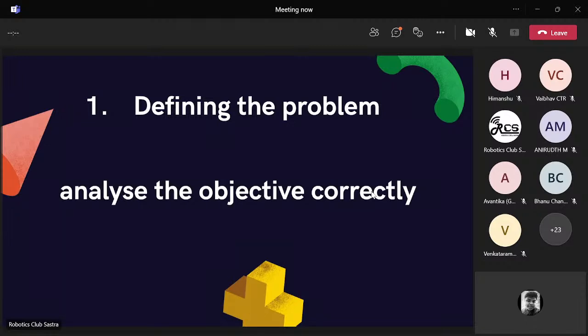So in this analysis, what we can say is we can't use temperature sensors all over the room to detect a person. Even in summer, some metal objects will have more temperature than the human body, so they will produce more heat. The temperature sensor will think that is the object, and imagine if there is a chair giving more heat, then the fan will continuously point to that chair instead of the moving person. So this statement says the temperature sensor cannot be used in this situation.